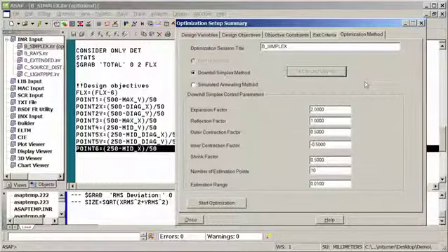In the downhill simplex method, what ASAP will do is form a simplex based on your number of variables. Since I have 2 variables, ASAP will form a simplex that has n plus 1, or 3 points, so triangles, located within a plane. As ASAP analyzes the value of the function at the 3 vertex points of the triangle, it will then flop over, expand, or contract the triangle in an attempt to find 3 vertex points that have better merit function values than the current set of vertex points.